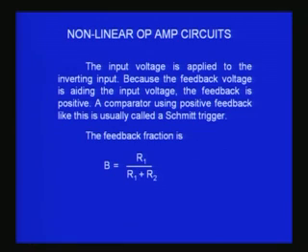What the circuit does is it is sensitive to some threshold voltage at the input, and the output will go to plus or minus voltage levels, two levels corresponding to the input, and there are two levels at the input for which this transition will occur, and the two levels are called LTP and UTP. LTP means lower tripping point and UTP the upper tripping point. So in this case, LTP and UTP are the V reference voltages corresponding to plus beta Vsat and minus beta Vsat.